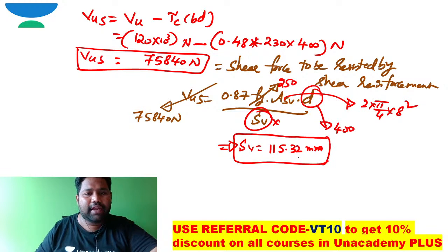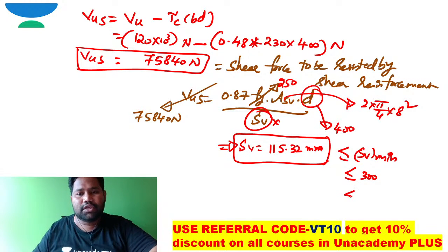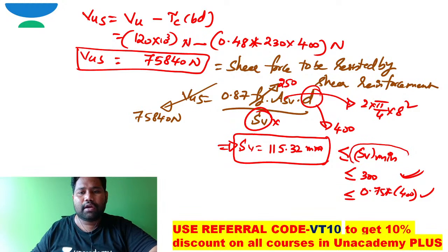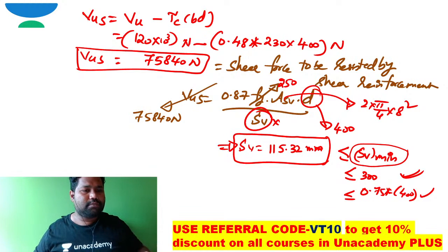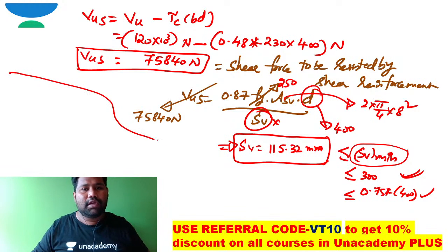But I cannot directly conclude this. SV should always be less than the spacing of minimum shear reinforcement. It should be less than or equal to 300, and less than or equal to 0.75 times effective depth d. If these two conditions are satisfied, I need to work out the spacing of minimum shear reinforcement.